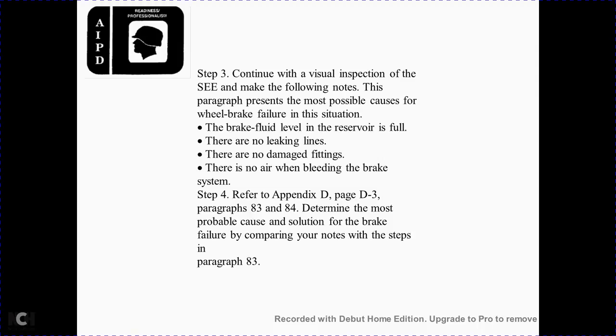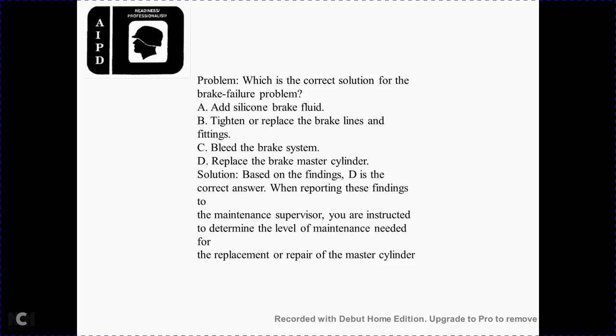Step 4, from Appendix D, page D3, paragraphs 83 and 84, determine the most possible cause and solution of the brake failure, comparing the notes of the steps in paragraph 83. Problem: when you are choosing the correct solution of the brake failure problem: A, add silicone brake fluid; B, tighten or replace the brake line and fitting; C, bleed the brake system; D, replace the brake master cylinder. Based on the findings, D is the correct answer.